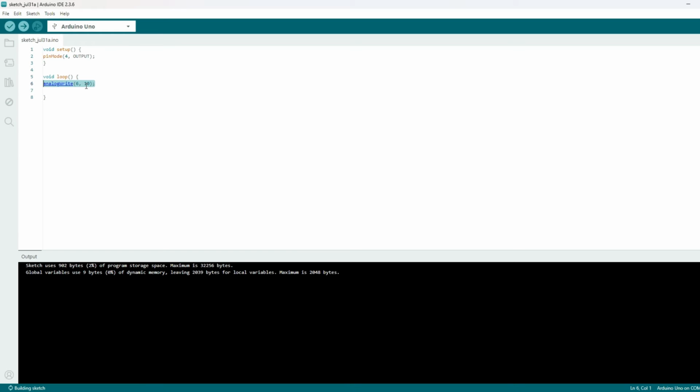So yeah, with this, you can modulate your power level, and if you want to see it change, you can actually paste a bunch of these and set it to say 50, and then 100, then 150, another 150, and then 200, and then 255. Let's add a delay of 200 milliseconds between them.